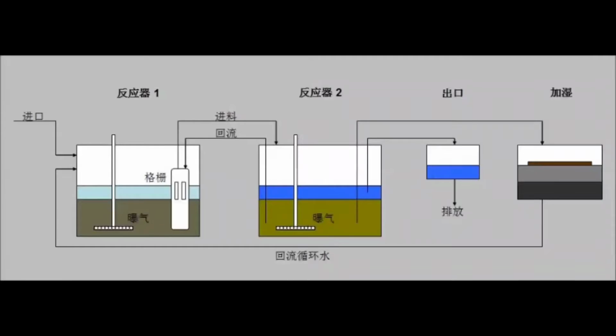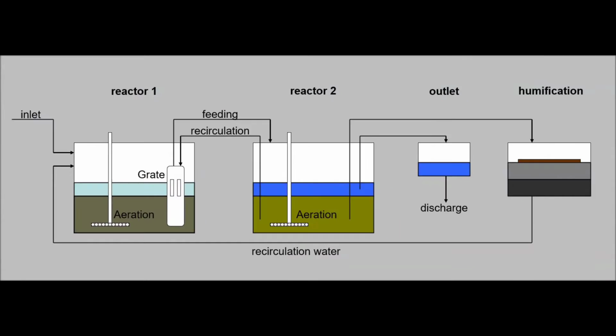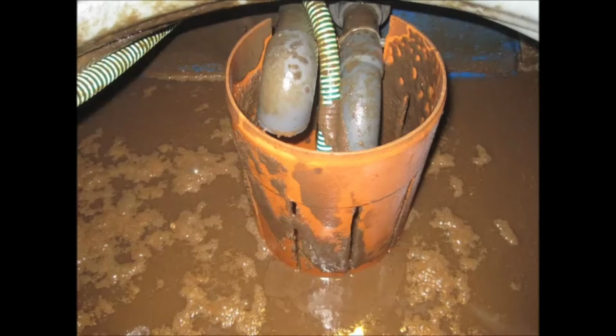Different microorganisms need different conditions. Some types of bacteria like oxygen. Some need an atmosphere where no oxygen is present at all. That is the reason why two different reactors are needed. The reactors offer different atmospheres for different bacteria. This ensures very stable processes and results in a far-reaching wastewater treatment. If the microorganisms are served a proper atmosphere, they form a brownish sludge, which fills the reactor.